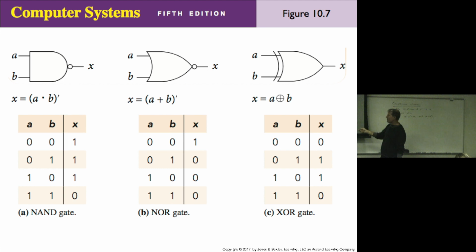So now, if the values of A and B are 0, 0, 0, 1, 1, 0, 1, 1, what would the AND be, in order? 0, 0, 0, 1. So inverted, that's what? 1, 1, 1, 0. Do you see how that worked? And now what gate is this?